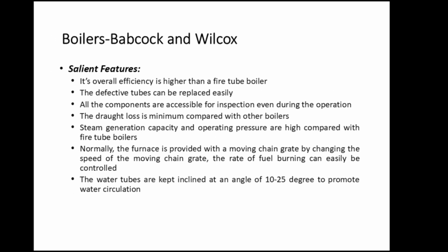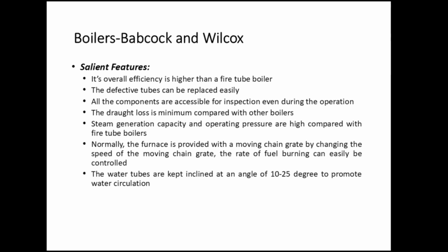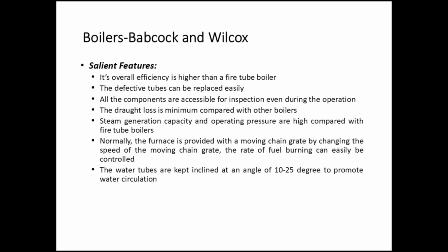Boilers. Babcock and Wilcox. Salient features. Its overall efficiency is higher than a fire tube boiler. The defective tubes can be replaced easily. All the components are accessible for inspection even during the operation. The draft loss is minimum compared with other boilers. Steam generation capacity and operating pressure are high compared with fire tube boilers.